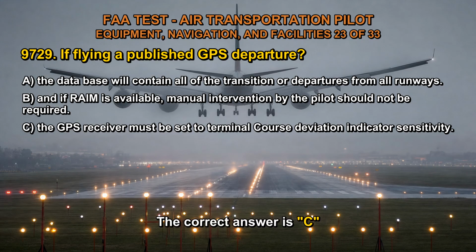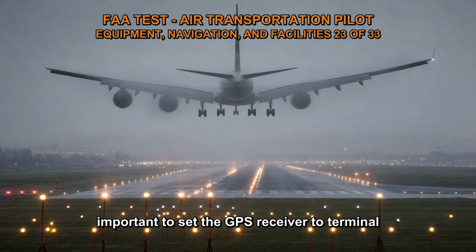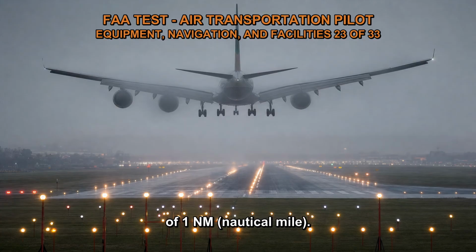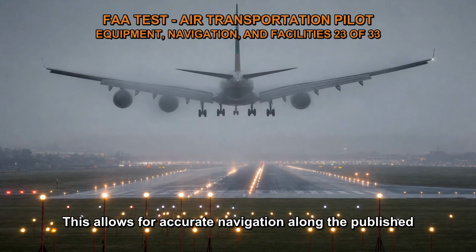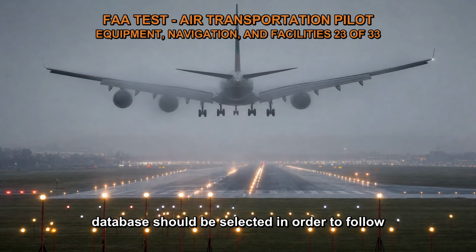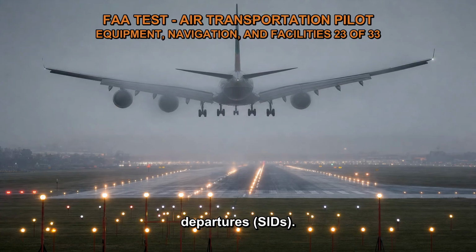The correct answer is C. When flying a published GPS departure, it is important to set the GPS receiver to terminal CDI sensitivity, which typically corresponds to a sensitivity of 1 nautical mile. This allows for accurate navigation along the published departure route. Additionally, the navigation routes contained in the GPS database should be selected in order to follow the published IFR charted departures and standard instrument departures, SIDs.